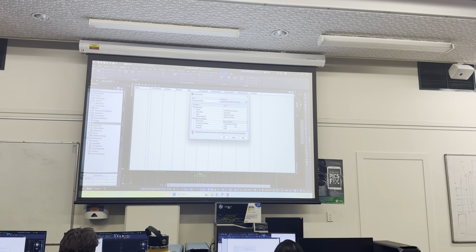So I would choose my existing ground as the base surface, and the comparison surface, which is the corridor. Just click OK. Here, we know that usually cut and fill is 1 to 3, right?